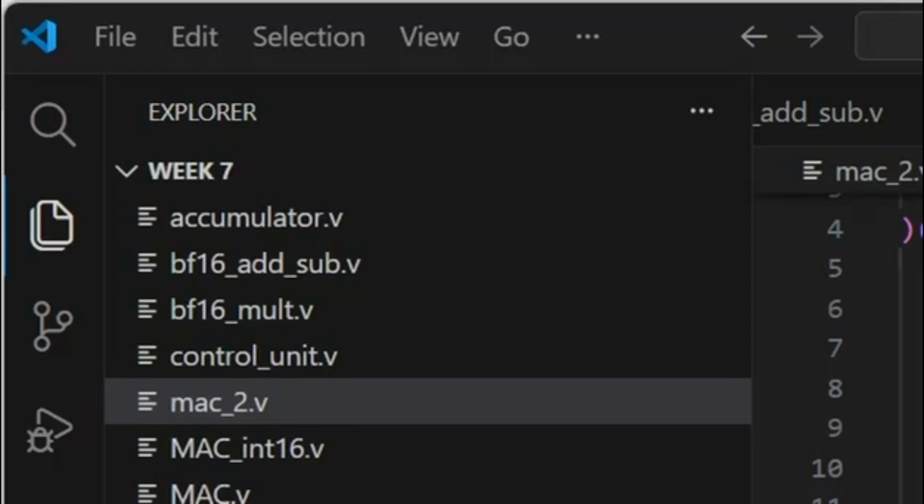We can also use a tensor core from a hardware accelerated point of view, where you need to do a lot of MAC operations to find vector dot products. Our application is more towards AI processing, which is basically MAC operations. For this, we are going with a bfloat16 based tensor unit. If we multiply two bfloat16 values, we get a bfloat32. We then add a C, which is also a bfloat16. I'll show you how we designed our MAC.